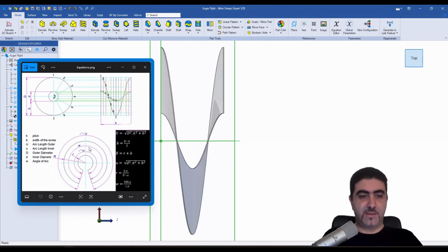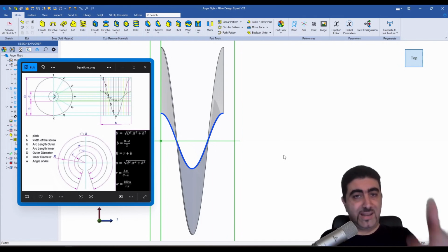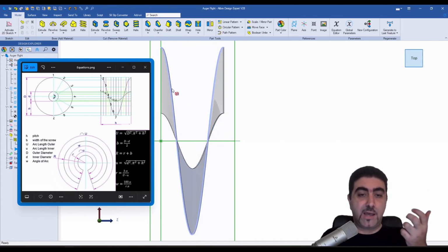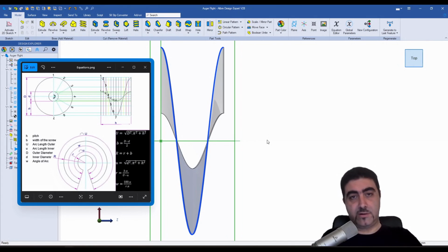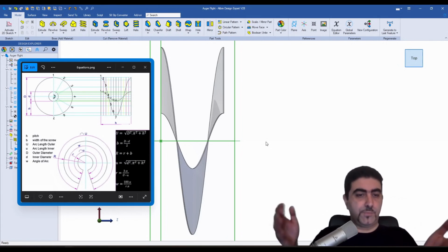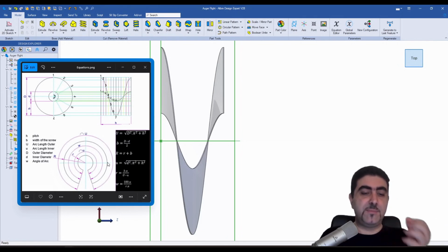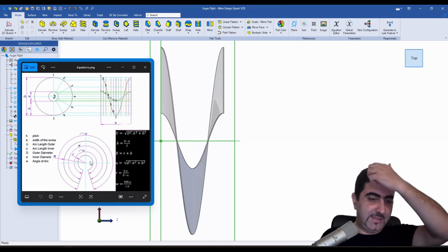So when we cut the shape of the flat pattern, we need to cut a circular shape that has a radius that would create this arc length. We need to cut an outer radius that would create this arc length, and then we need to have a constant width of what we just measured, which was 105.55. And with these three parameters and constraints is how we get this C shape, which is the flat pattern of the auger flight. And that's why you get this little opening here.